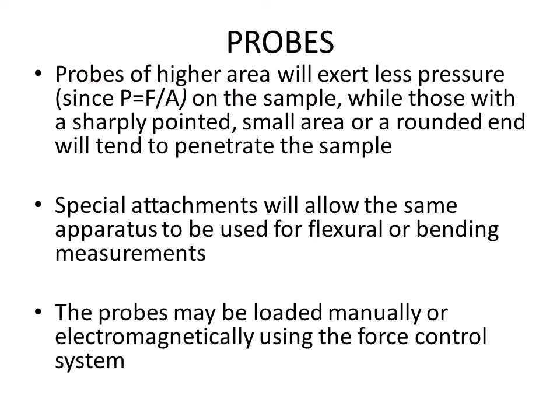And some more information about probes is listed over here. Probes of higher area will exert less pressure on the sample. Higher the area of the probe, lesser the pressure on the sample, because we know that pressure is equal to force applied per unit area. So greater the area, lesser will be the pressure. While those with a sharply pointed or small area or a rounded end will tend to penetrate the sample. So if the probe has this type of shape, when stress is applied, it may penetrate the sample. So these things must be kept in mind.